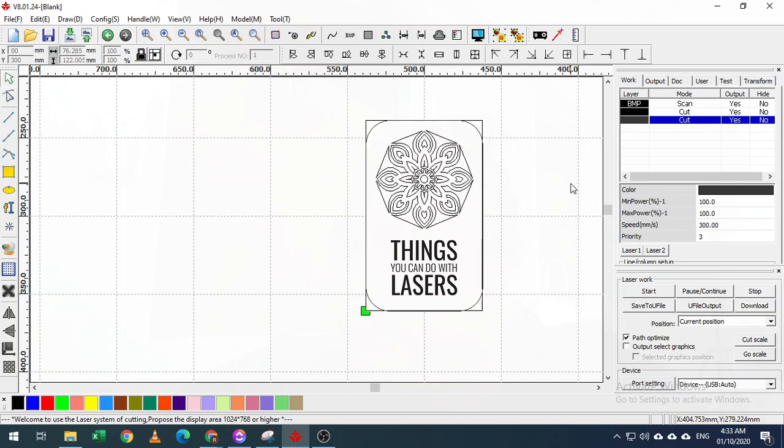For scanning, the principle is you set it with say mid to high power, and then you work really fast so that your material won't be burned, while at the same time leaving a significant depth for the engraving. And for the cutting, the general idea is that you move rather slow, and your laser output would be high.